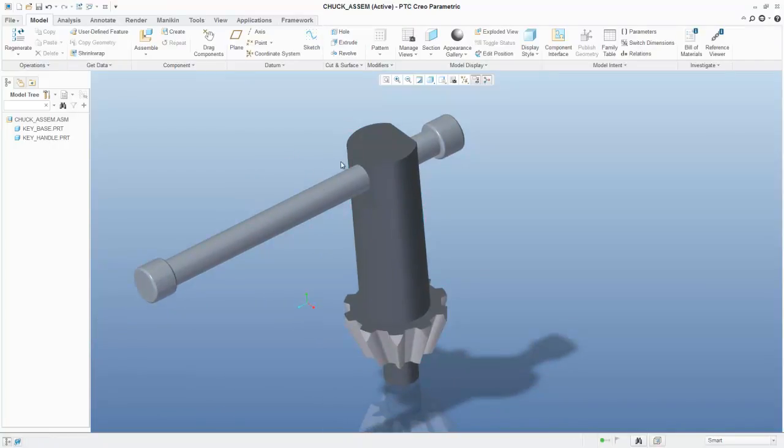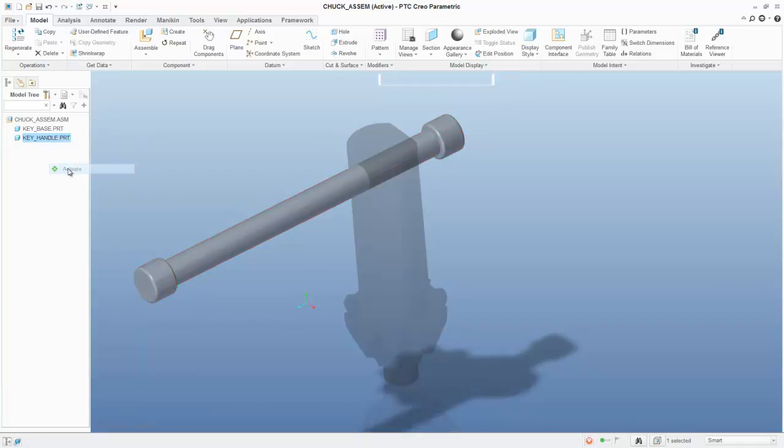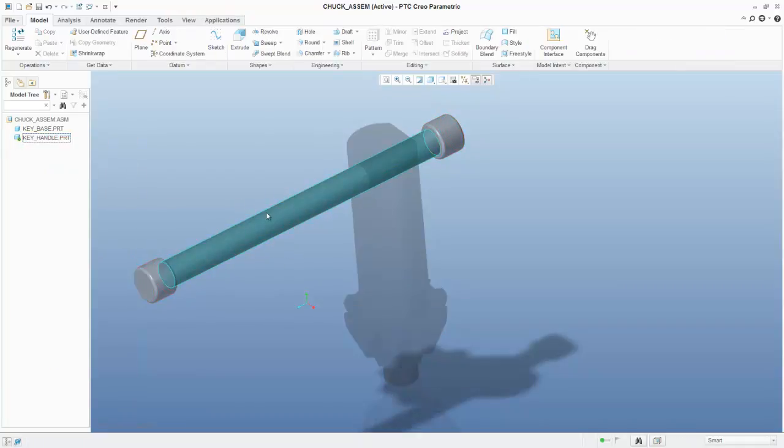Okay, and there's a few things you can do inside the assembly as well. You can actually make geometry changes with the actual parts. In order to do that, you can't just click the part and change, obviously, the constraint, but you can't make changes to that part. In order to do it, you have to activate it. So if you right click it and go to activate, it suppresses essentially the other parts, and you can double click this and actually make a geometry change.